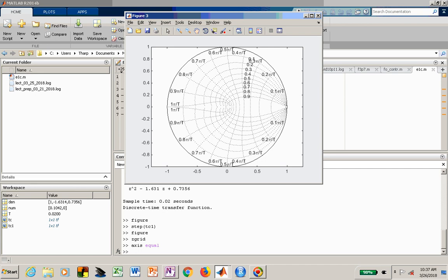In this case, you see the first one from z equal to 1 as you go up in angle is at 1/10 pi over T. The biggest frequency that we can have, over at -1, is pi over T. We've subdivided that 180 degrees into 10 different angles, so at 1/10 pi over T, the angle is omega sub n times T on the unit circle, and in this case it would be 0.1 pi over T times T, or 1/10 pi, or 18 degrees.